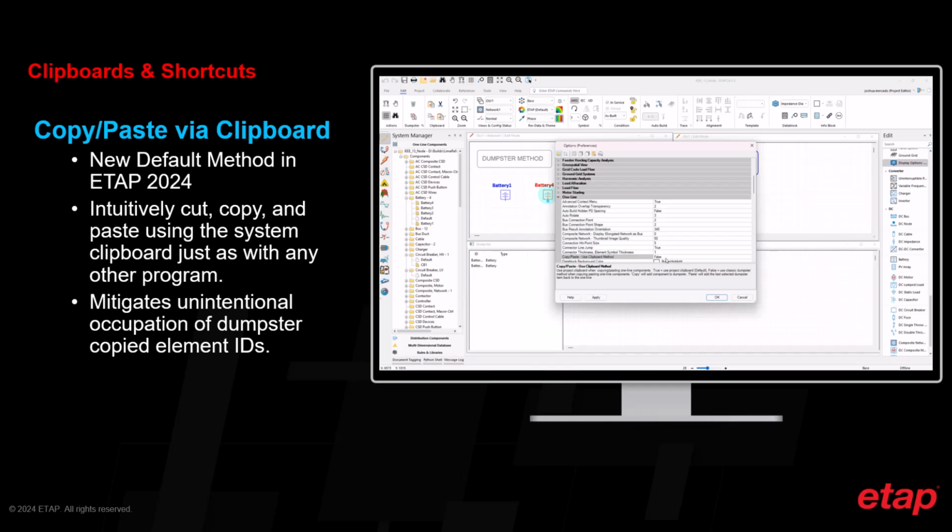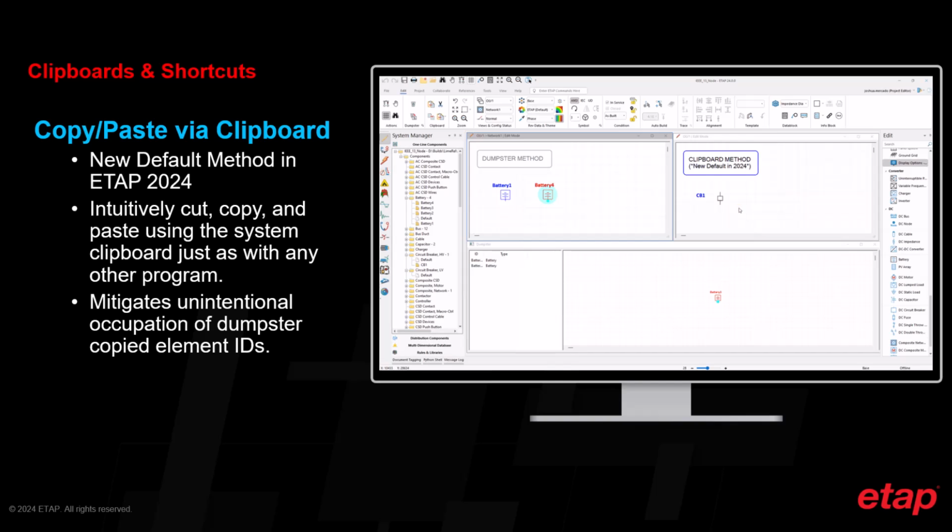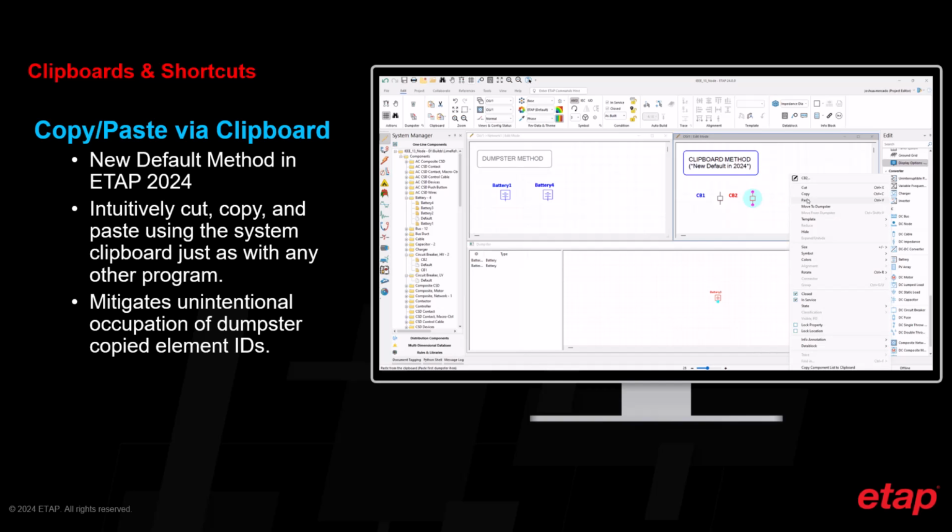In version 2024, this method of using the clipboard was set to default, meaning that on the one line, when a component is cut or copied, no elements are added to the dumpster. Here, CB1 is copied and pasted, resulting in CB2 directly without any added components in the dumpster. Similarly, cutting CB2 does not send it to the dumpster. This behavior makes cut, copy, and paste much more intuitive and in line with already existing clipboard functions in other programs.